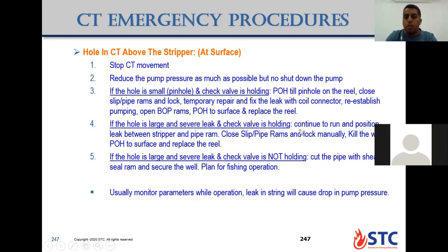In this situation, instead of pulling out, you will continue running inside the hole and position the leak point between the stripper, which seals from above on the outside, and the pipe ram. So you close the pipe ram, and you place the area of the leak between the stripper and the closed pipe ram. So here you will close slip and pipe ram and lock manually.